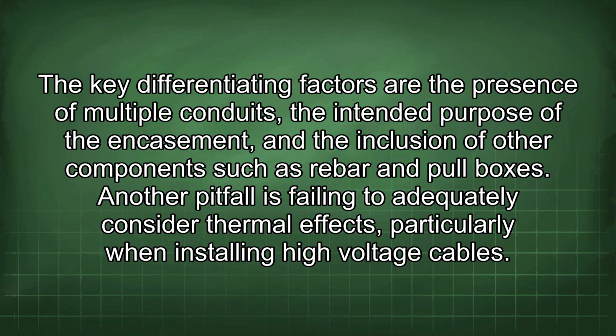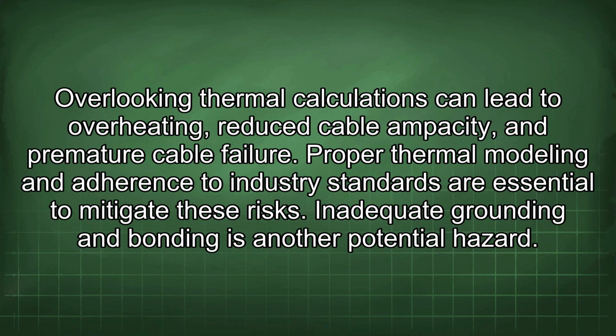Another pitfall is failing to adequately consider thermal effects, particularly when installing high-voltage cables. Overlooking thermal calculations can lead to overheating, reduced cable ampacity, and premature cable failure. Proper thermal modeling and adherence to industry standards are essential to mitigate these risks.